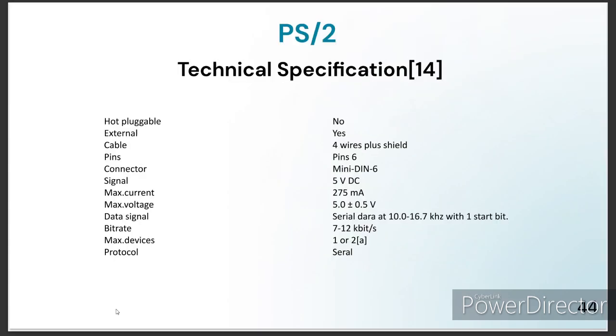Technical specification: hot pluggable, no. External, yes. Cable 4 wires plus shield. Pins 6. Connector mini DIN 6. Signal 5 volt DC. Protocol serial.